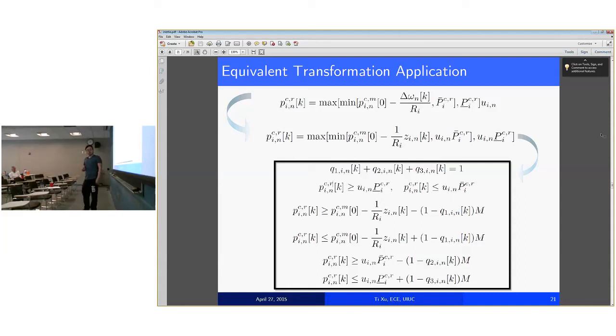So I use 5 seconds as the dynamic simulation period, and I use 0.05 second as the time resolution in the dynamic simulation. It means I have 100 substep periods for the dynamic simulation. And I tested the time a little bit. I'm not the optimization designer, so I purely use the functions of my lab.